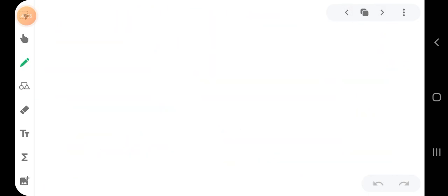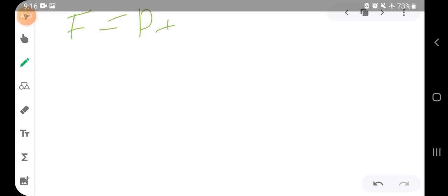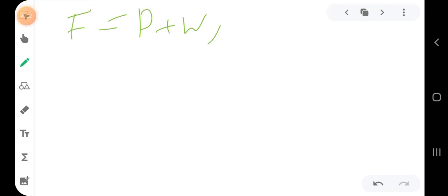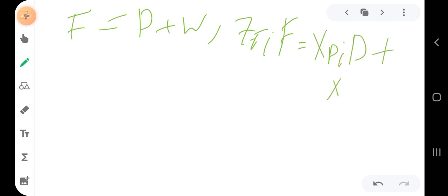You will say that F is equal to D plus W, and then ZF of component I times F is equal to XDI times D plus XWI times W. So you have two unknowns, D and W. You can solve for them if you know this XDI and XWI, or only if you know the percentage recoveries. So this is a way to get this D.